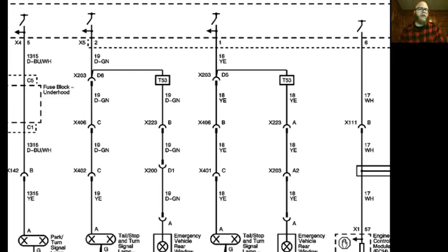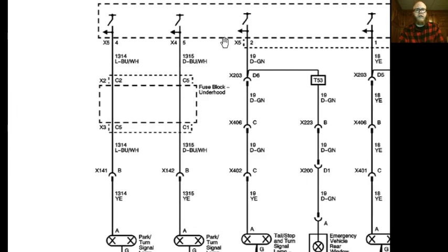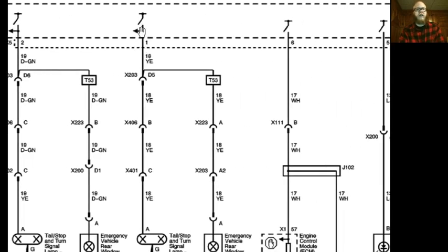So if I hit the brake pedal, the module gets the input that the brake pedal has been depressed. It's going to then try to output to my stop lamps, and it sees that this stop lamp here on pin 1 of the connector going into the body control module, sorry to move you around so much, doesn't change state from 0 to 12 or 14 depending on how this is controlled, and it can actually set either a code or maybe the dummy light on the dashboard comes up and says that you have a tail light out, because it's kind of hard to tell if you have a tail light out because you're not really looking that way. So this is how the computer can monitor itself. This is how codes can be generated, and we're going to get into that kind of stuff next week, which I hope you're excited for.